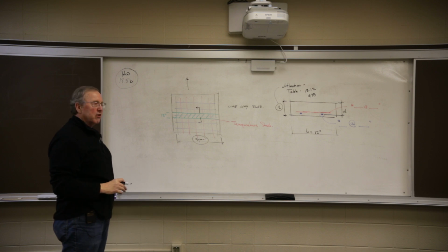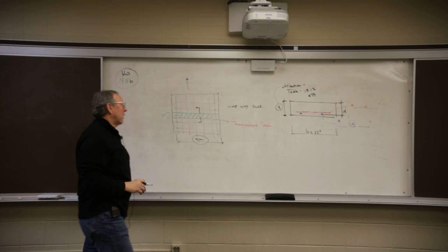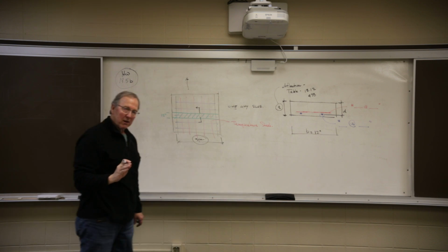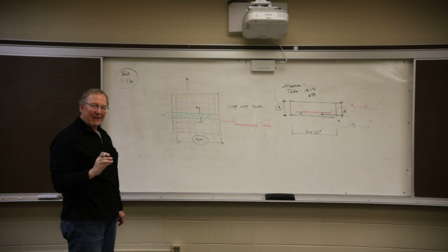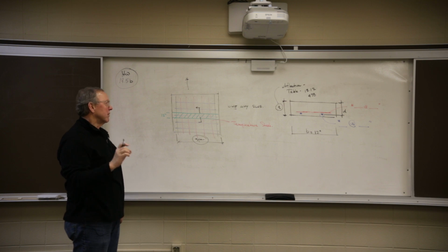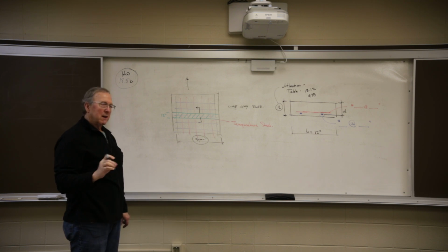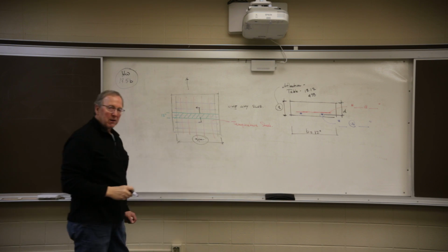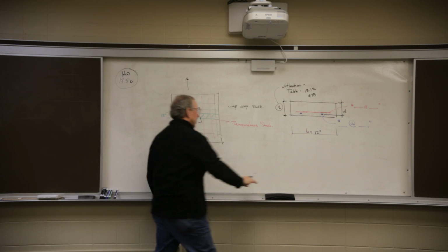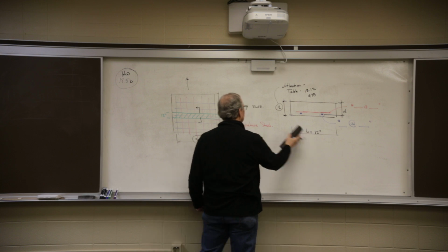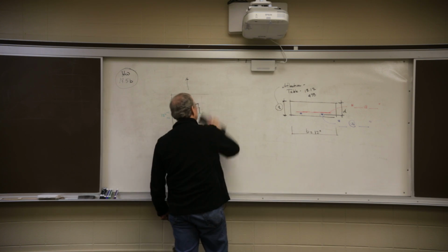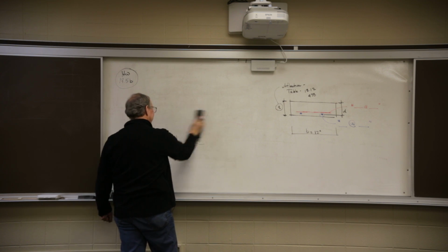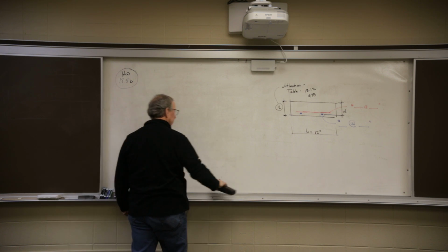And this design is exactly the same. So we've got a one-way slab. One way, not the direction. It's the direction of the main steel. The main steel is going one way. So this is not main steel. The red bars are not main steel. They're temperature steel. Okay, so I'm going to leave this little picture over here. Remember, B is always 12. D is directly related to T.